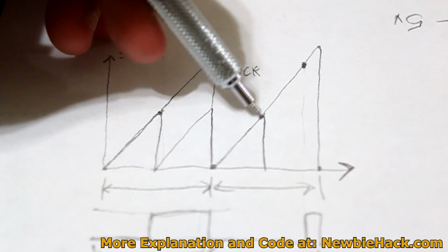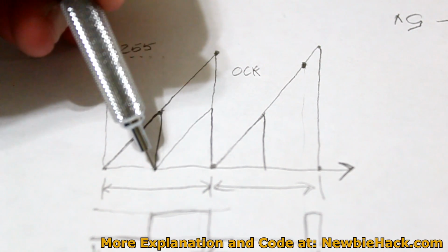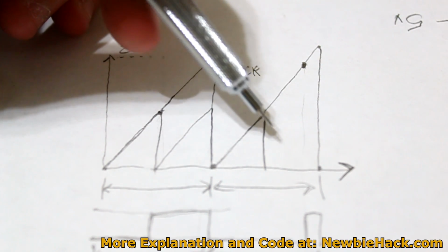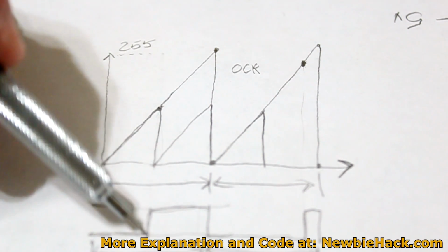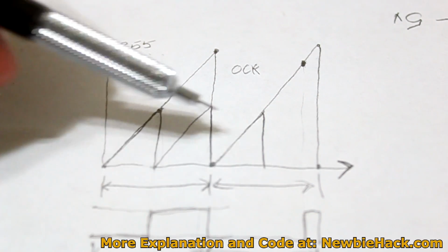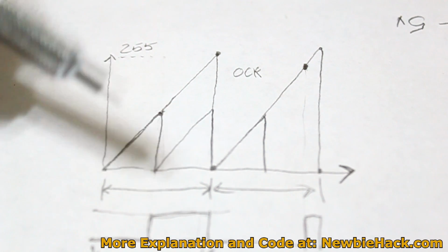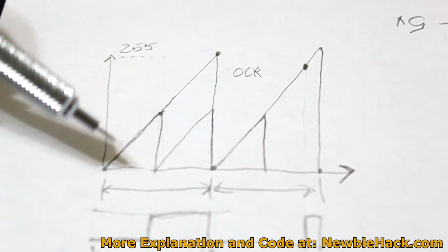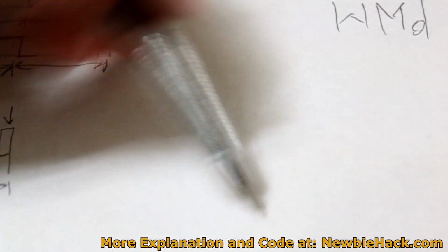We can probably achieve a 50 hertz or a 20 millisecond period doing this with prescalers, but then we wouldn't be able to use our OCR as a way to create our pulses. So we would need to do this more of a manual approach, and we'll get into more detail in another video. For the servo, we'll be using the 16-bit timer.